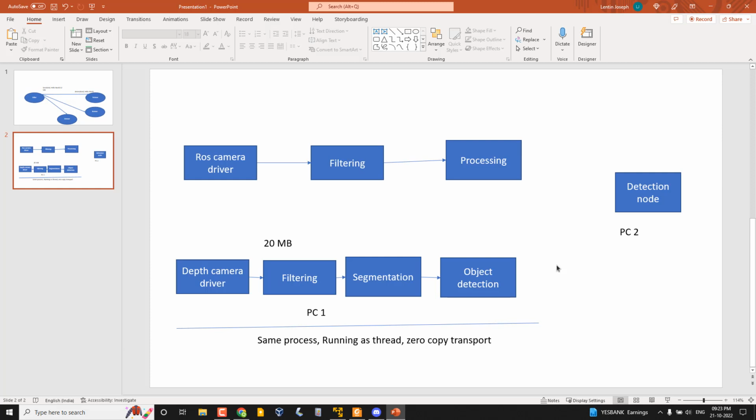So that can reduce the effective delay. In ROS 1, it is using TCP/IP, specifically TCPROS, which heavily uses serialization, but DDS is much better than that. It's actually using the shared pointer as well.